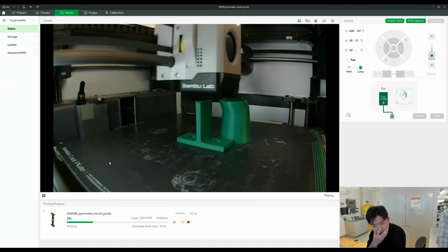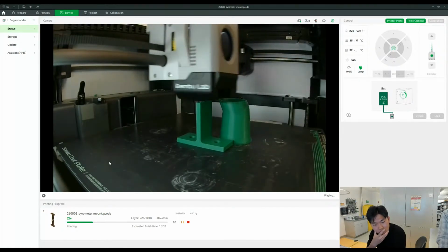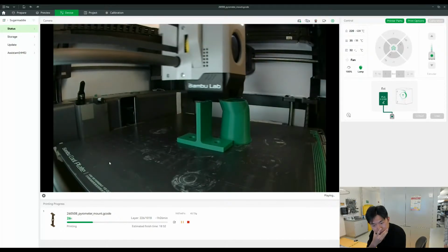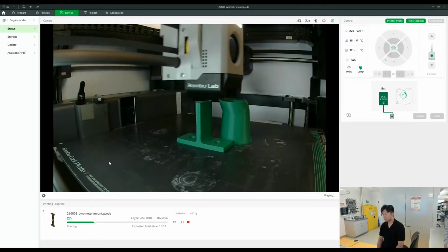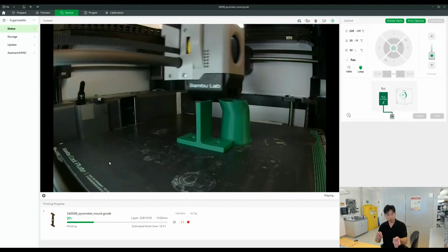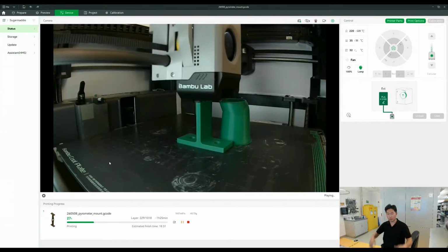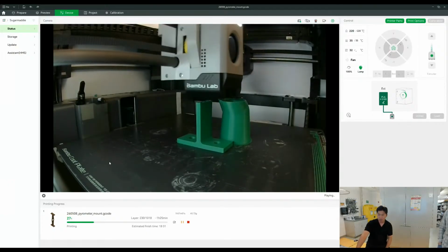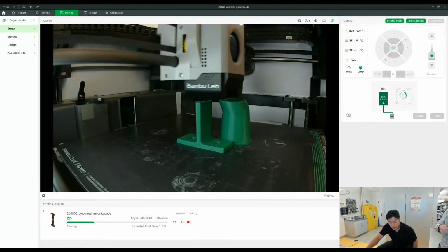That would be so much easier than flipping a relay on and off and finding a stable point. With the amount of current you have when you're flipping it on and off like that, I think it's making all that electrical noise, and that's part of the problem. Right now it's literally just the knobs turning, but with the old relay, yeah, correct. Right now, the issue we see is that oscillation. Versus when you use a dimmer switch to control your lights, you get it really smooth.